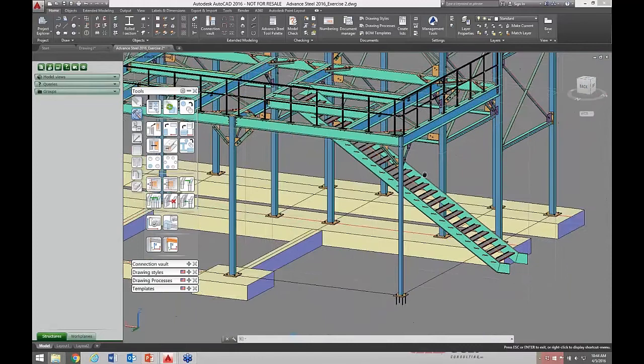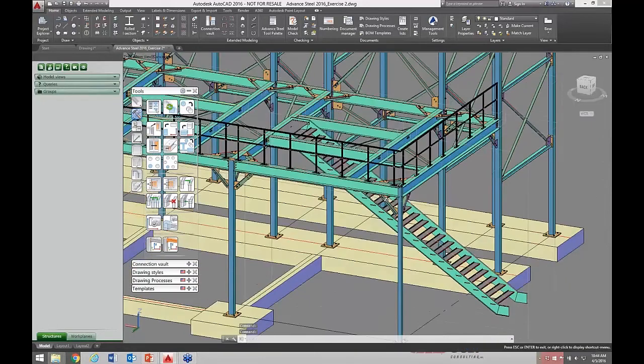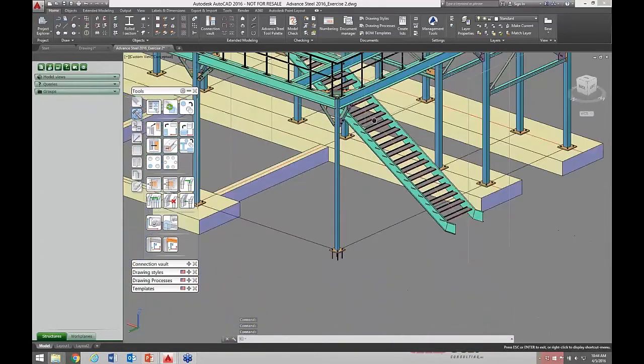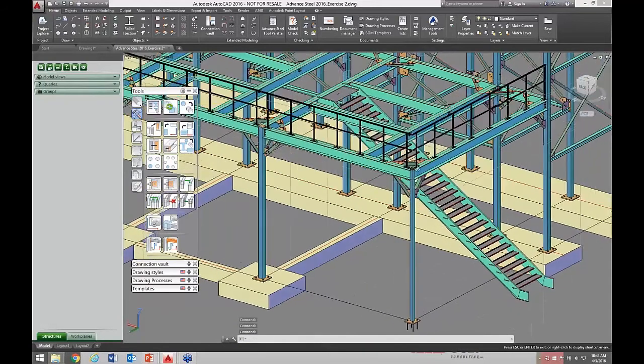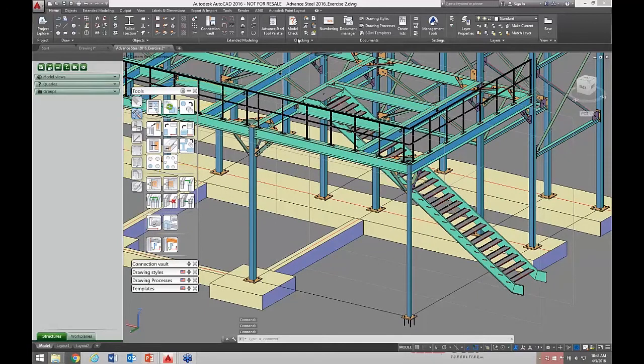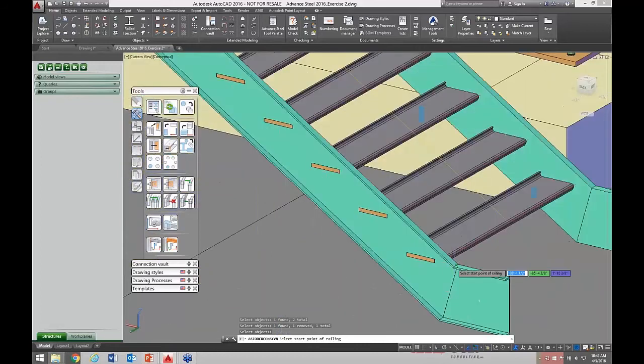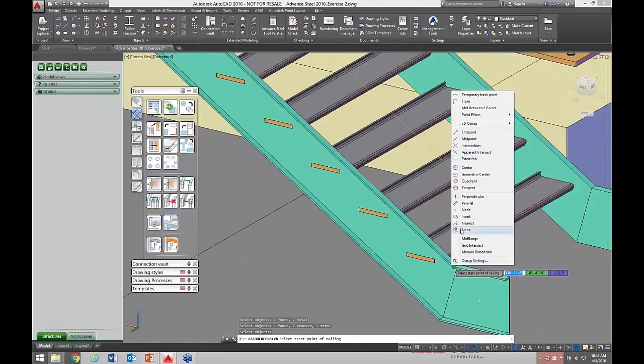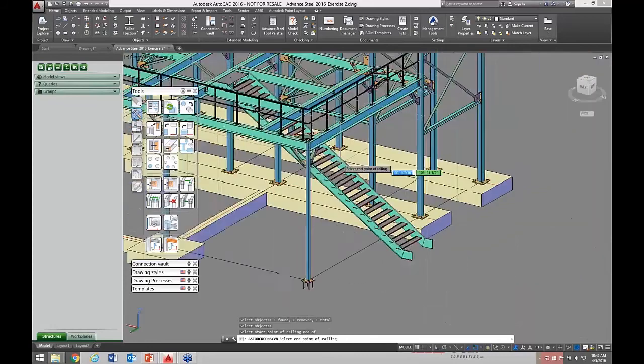So let's go back to the stair itself. Let's put a rail on here just to see that it's looking for that beam association. And a stringer, as far as Advanced Steel is concerned, is another beam. Let me pick my members. Got to remember with the particular one I have whether I need to pick that or not. No, I think I don't. Let me make sure I unselect that one. And depending on the condition, I have to select appropriately to define this macro.